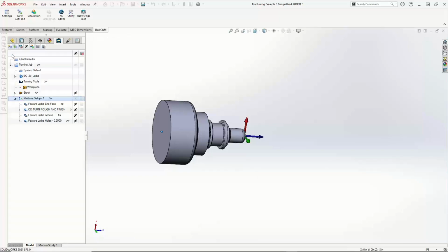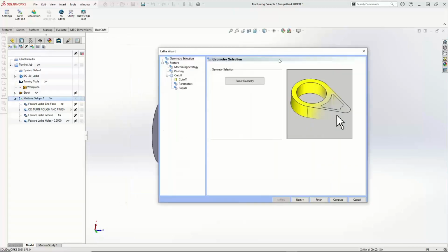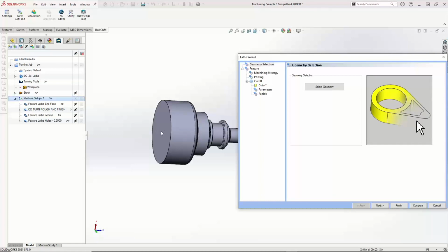And then hit OK. Now, if you didn't draw that snap point, or if that point was shifted up to, say, here, you're telling it where to cut off in both X and Z. So by picking the middle point, it's going to cut off all the way back here in X and all the way to the center for Z. Or, sorry, I did that backwards. All the way back here in Z and then all the way down in X.